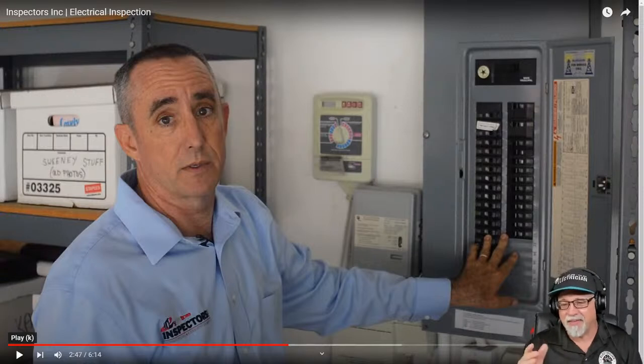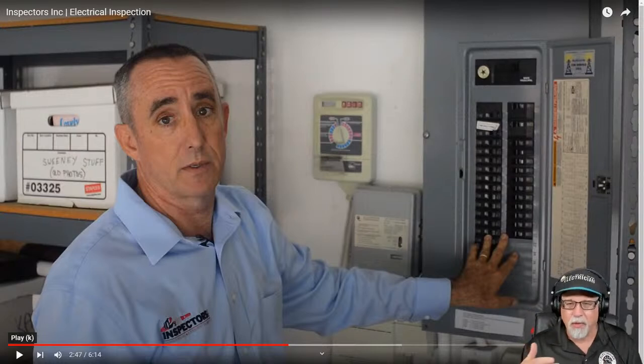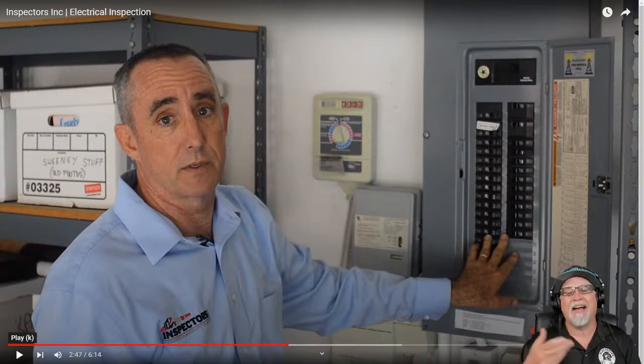And the reason I bring that up is because he says it does a pool, spa, the house itself, and I just want to let people know we do load calculations to determine whether or not that 200 is adequate or not. It's all based on a load calc. Article 220 of the NEC, Part 3 and Part 4, Part 3 being a standard method, Part 4 being an optional method. We have to understand it.